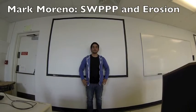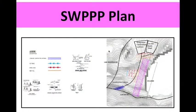My name is Mark Moreno. I do the strip and erosion control plan. The basis of this design was to prevent any contaminated runoff coming from the designated construction laydown and on-site batch plant into the adjacent creek located here on the dam. To prevent this, we added gravel bags along the length here, followed by fiber rolls coming down the slope as seen in the topography map.